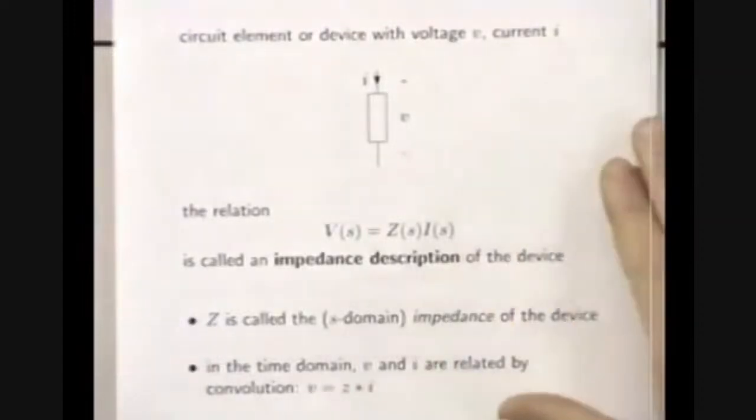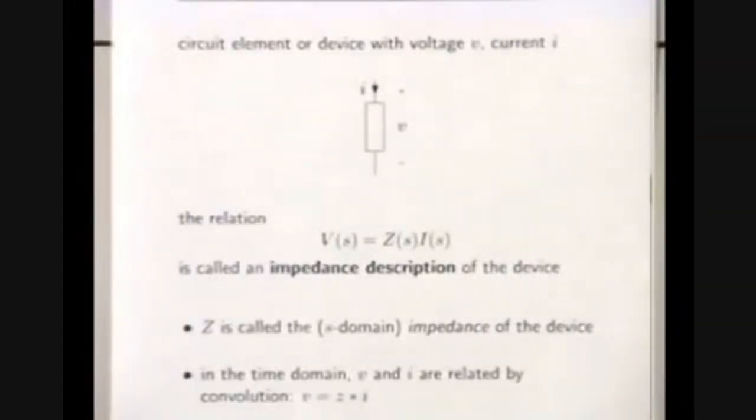So this is not unlike, in fact, it's just one step beyond sinusoidal steady state and phasors. There, you extended static analysis to sinusoidal steady state analysis by assuming every current and voltage was a sinusoid. You then represented its amplitude and phase by a complex number. And then you observed that even complicated things like inductors and capacitors could be expressed by a relation that looked very much like a resistor relation, or Ohm's law, except that everything is complex. Okay, so this is really the exact same story, except it's a little bit more complicated now. Everything inside is a Laplace transform.